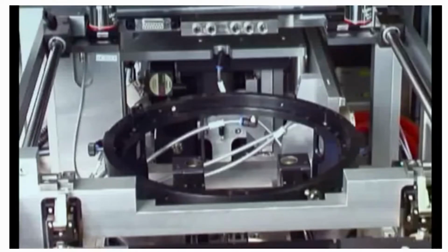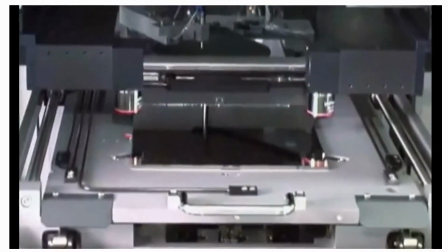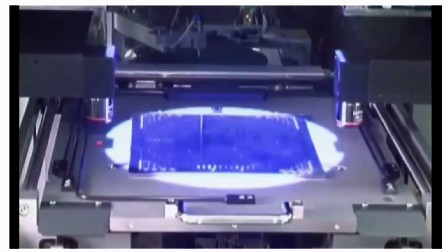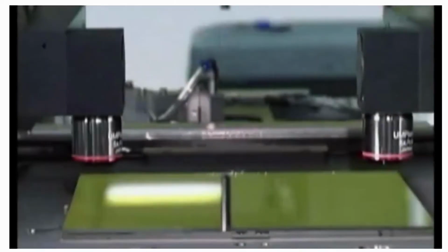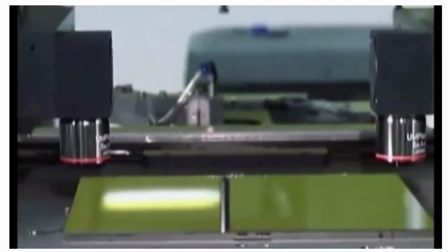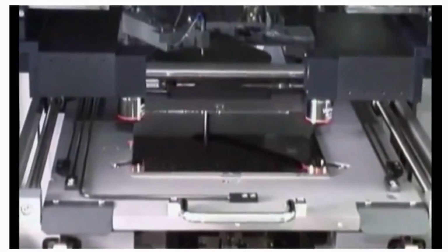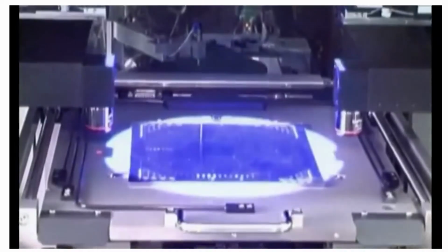Because of the MA200 Compact's newly designed microscope, during exposure, the mirror housing doesn't move forward. The microscopes only move sideways, thus reducing the vibrations of the alignment stage to a minimum, resulting in far greater accuracy. The optics of the MA200 Compact are optimized for thick resist processing. In thin resists, it achieves a resolution of 3 microns in proximity mode and a sub-micron resolution in contacts printing.